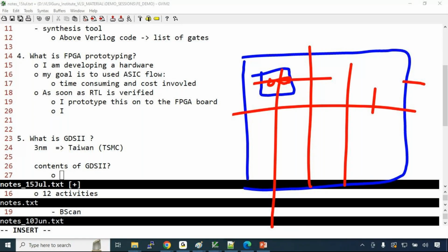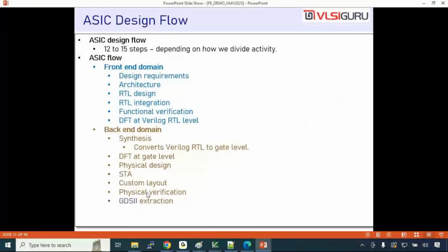At this layer, you deposit oxide. At this layer, you deposit metal. At this layer you deposit gate. Okay, that file is called GDS2. Have you got an idea? Because only if you give that level of information, if you give a very large code, will they be able to manufacture? All right, you need to tell them at the very lowest level, take silicon, first do the etching, then do oxidation, then at this point deposit metal. That information is what you get in the GDS2. Okay, fine. That is what you get after physical verification.